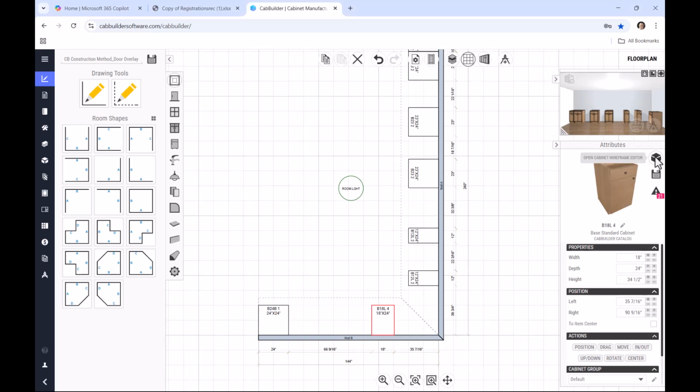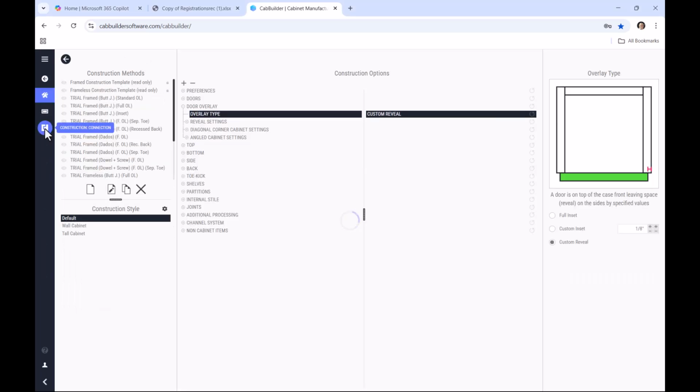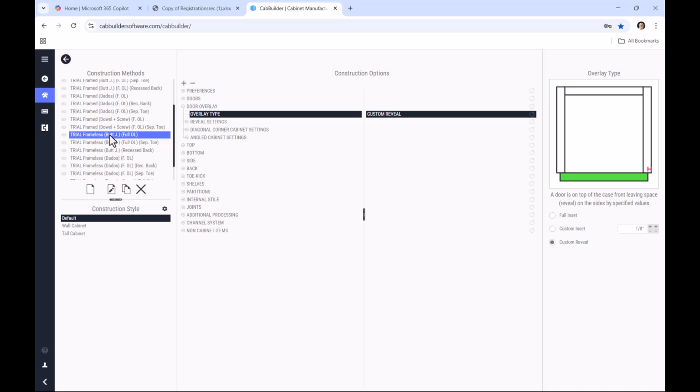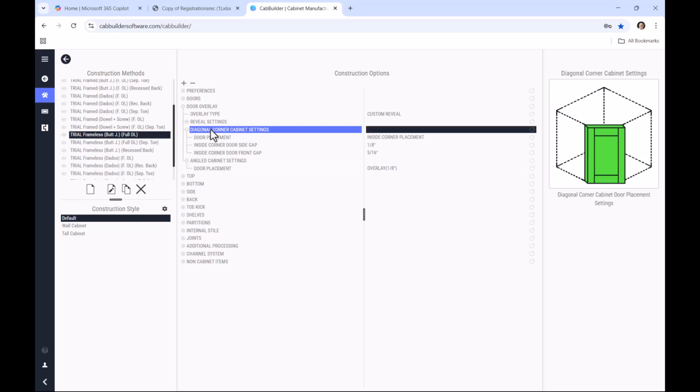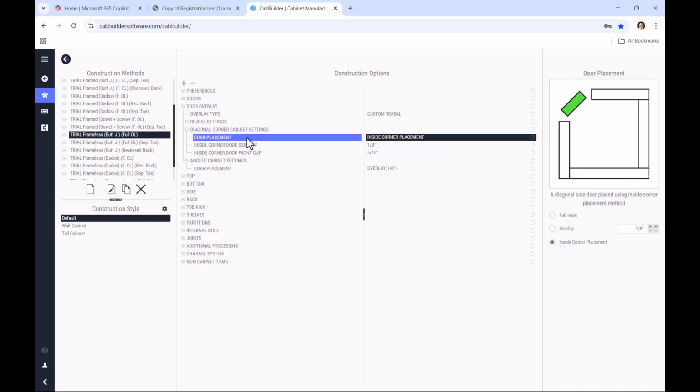Frameless setups will need special attention for diagonal and angled corner front calculations. These doors maintain the same top and bottom behavior, but can interact with the cabinet sides in several ways, mostly depending on the special hinge type assigned. The first type is a full inset setup, which should be selected when you have an overall inset style.